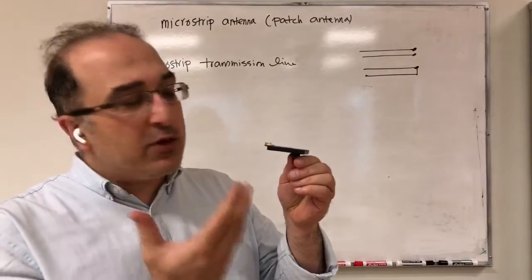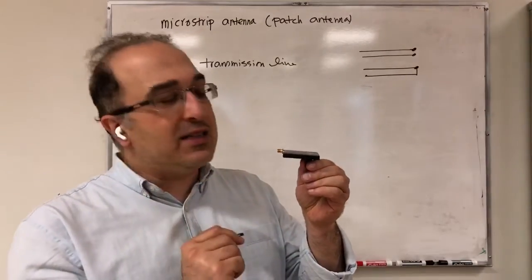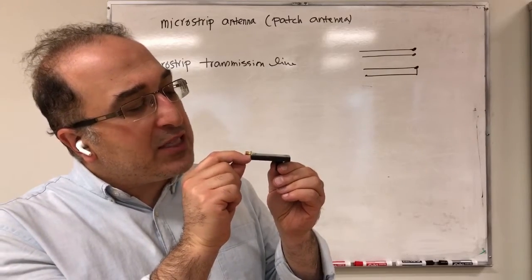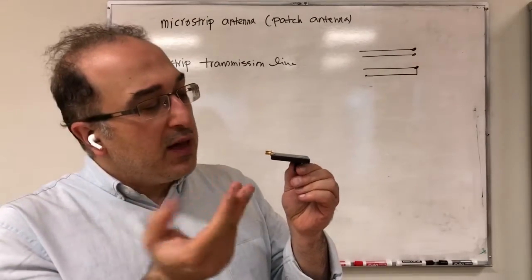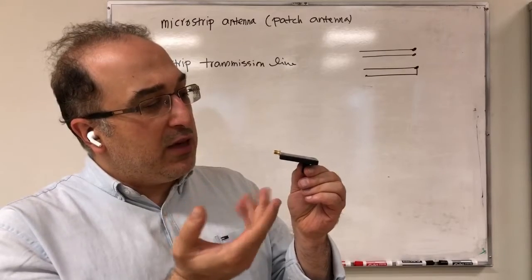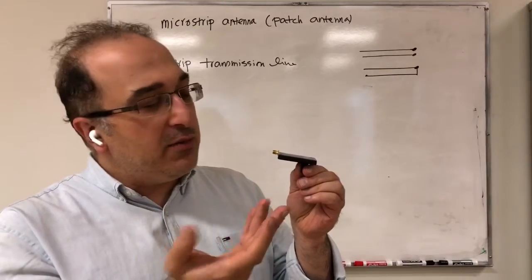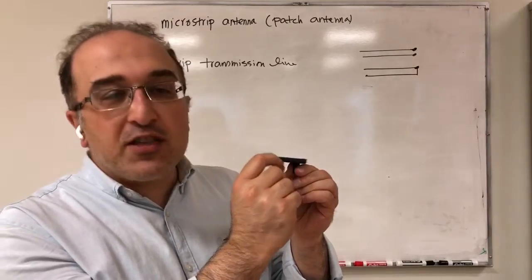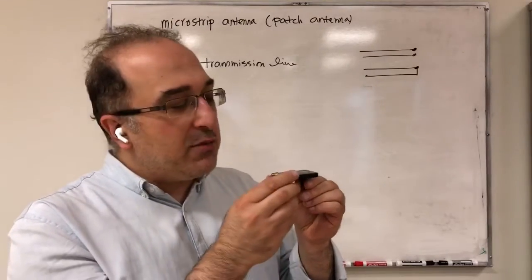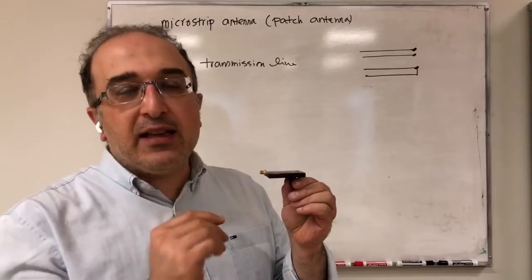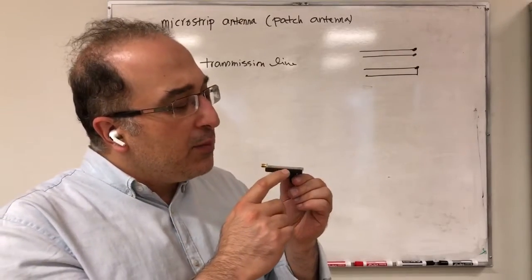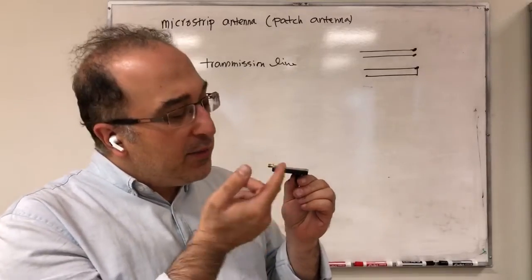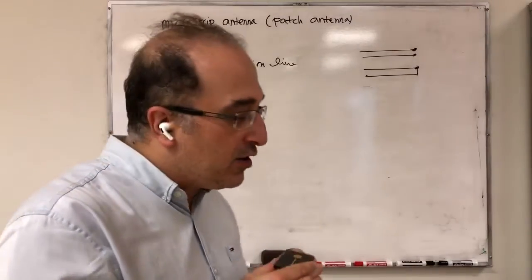If you look at this, I don't know how well you can see it in the video, but the thickness of this is so small, in the range of maybe just a few millimeters, maybe 1 point something millimeter, let's say 2 millimeter, and the rest is essentially just something to hold this for measurements as we needed to mount the antenna. But essentially this is extremely thin, and in the back of this you have your other conductor.